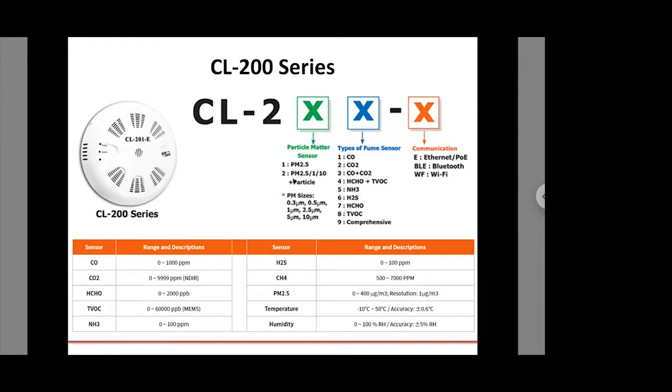So it will log from a variety of those sensors and include date and timestamps, and these are able to store up to 450,000 downloadable records. These modules communicate wired and wirelessly with Ethernet, RS-485, Wi-Fi, and Bluetooth. Many of these modules offer a combination of communication methods. The CL210WF, for instance, offers RS-485, Wi-Fi, and Ethernet with PoE.